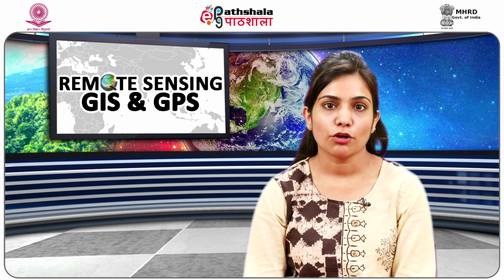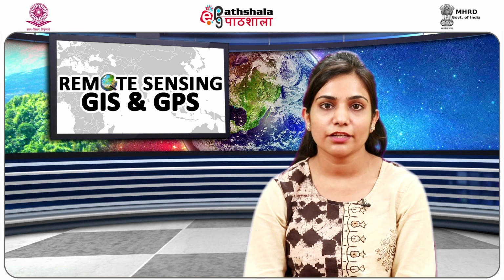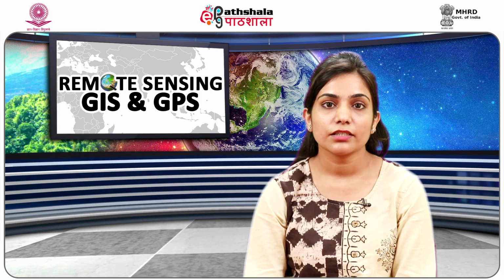Photogrammetry is the technique of determining the geometric properties of objects from photographic images, where the 3D coordinates of points, features or objects can be determined by measurements made in a stereo pair using the principle of triangulation. The essential elements required to produce a digital orthophoto are photo-identifiable ground control points, and camera calibration and orientation parameters. Camera calibration is the process of estimating parameters of the camera using images of a spatial calibration pattern. The parameters include camera intrinsics, distortion coefficients and camera extrinsics.